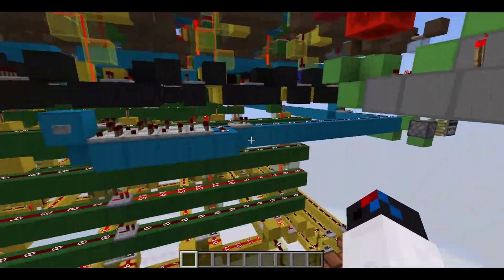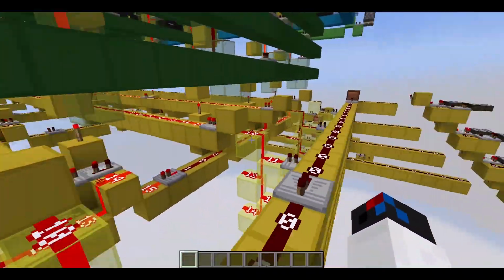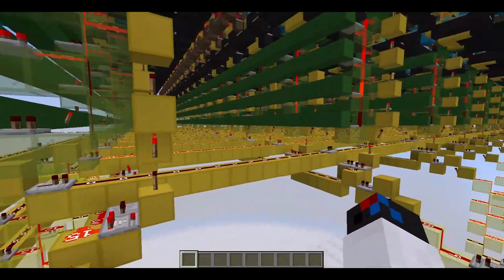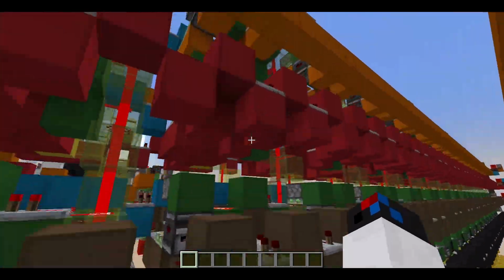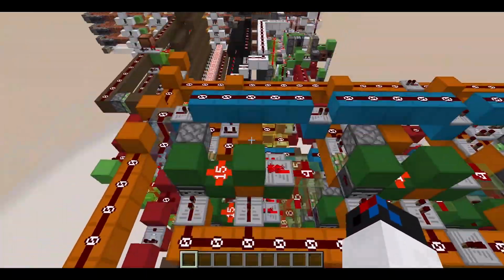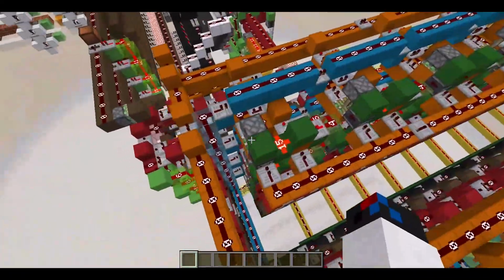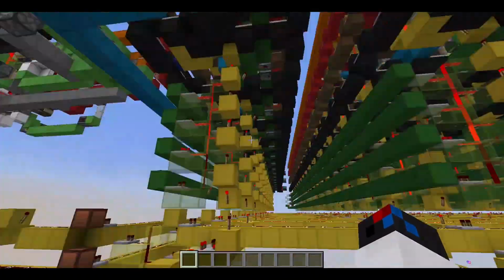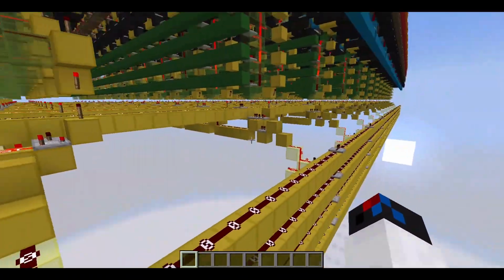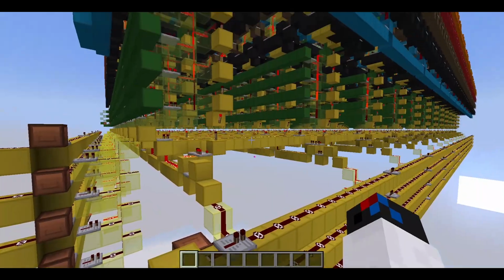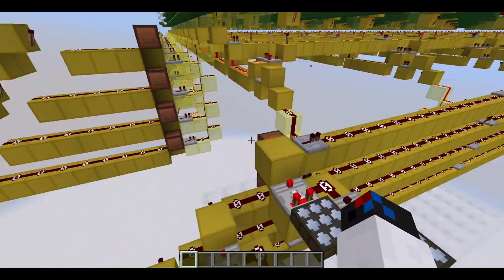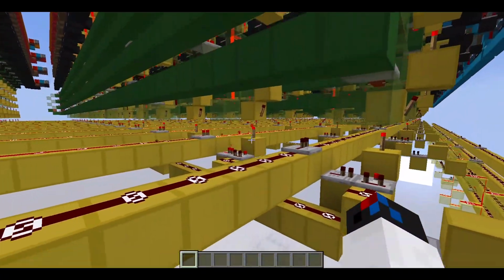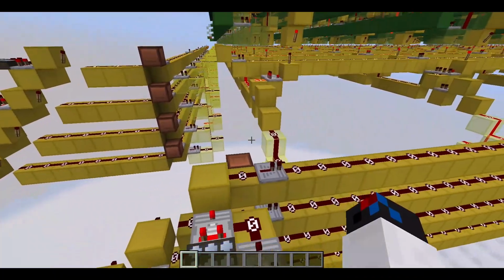And now is the dumb part here, this yellow part right here. What the hell is this? Well, this is actually how we can select individual cells in the instruction table, because remember, we need to select each cell every cycle in the instruction table, right? And this is how we select the cell in the instruction table. And it looks complicated, but don't worry, it is not. This thing is actually just a very big matrix decoder. Now that sounds complicated, but it's not, okay?